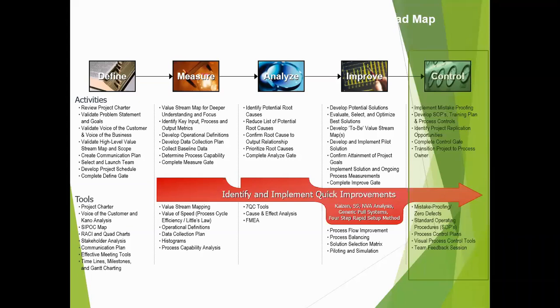We're going to put a person in charge to monitor the process and the progress. And we should also put some controls in there, an alarm to warn the person in charge, who should be monitoring the process and the progress, to see if everything's going within the parameters between the UCL and the LCL.